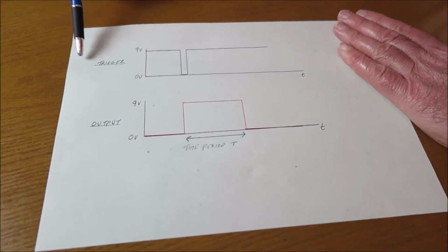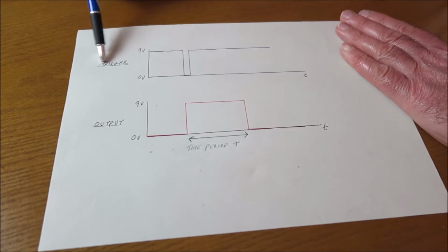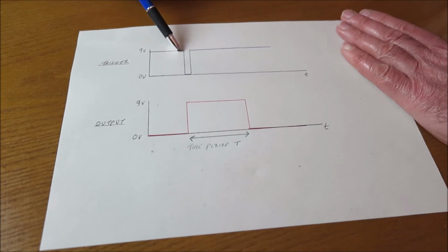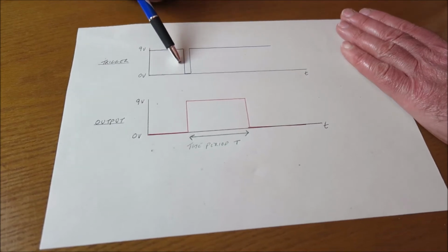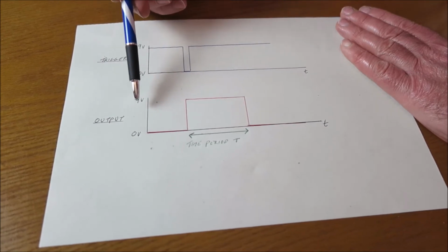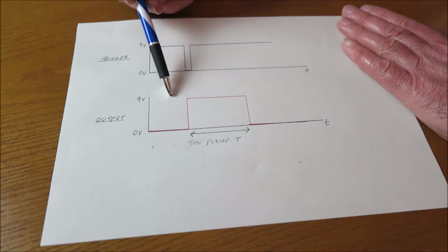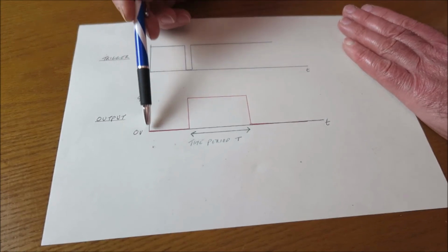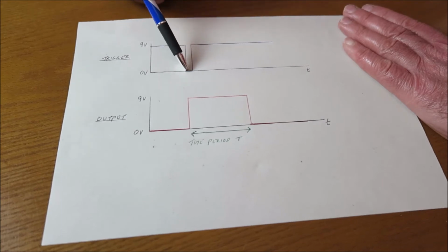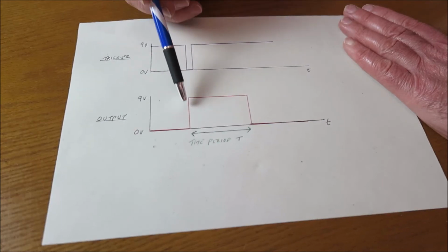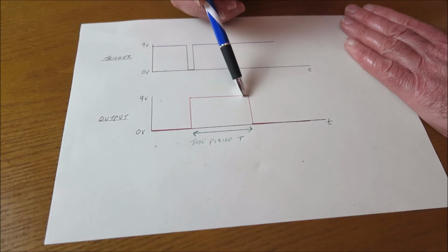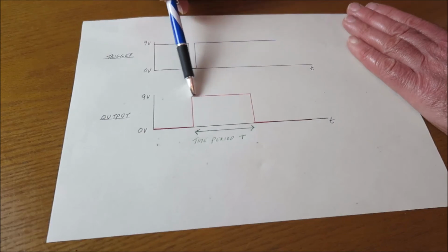So this is what was happening on the oscilloscope. So you've got the trigger. So this is where we do the switch. So the switch is held high at 9 volts. When we trigger the switch, it briefly goes down to 0 volts and then back up. But what we start at the output is the monostable period. So you can see if we follow this along, at the period when the switch voltage drops down to 0, that's triggering the device, it initiates the time period, the monostable period, and we can actually calculate this period.